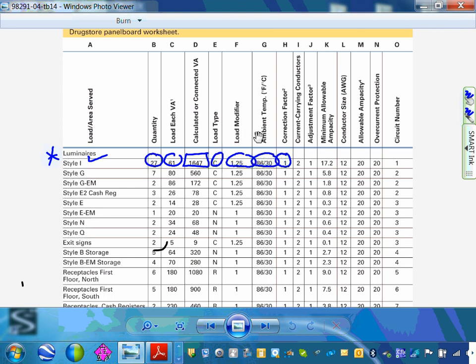Okay? Now, carrying conductors. How many carrying conductors do I have? 2. Do I have to worry about derating because of bundling for 2, 3 or less? No. If I put a 4, then we're doomed. Okay, then that number here is 1 because we don't derate. Now, I'll pick on you, Gary, again. Now, suppose I have the number here instead of 2, 5. Can you guys go to the next table that gives you bundling? If there were 5 of them, what would that number be?